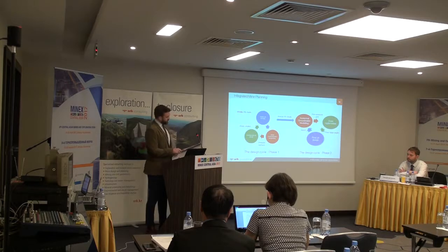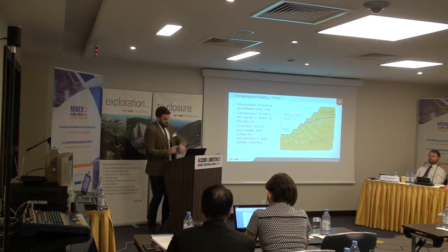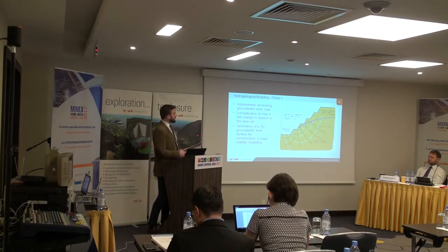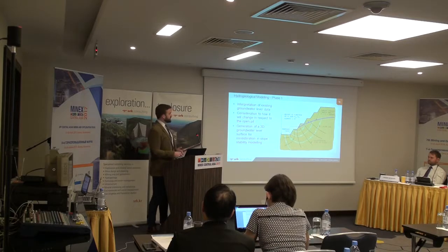So I'm just going to talk you through some of the elements for the different disciplines. As I said, for the phase 1 hydrogeological modelling, we would carry out a field investigation and try and work out what the existing groundwater level is at that deposit, and then try and give some consideration to how it would change in respect to the open pit.